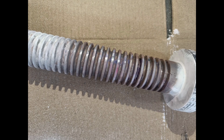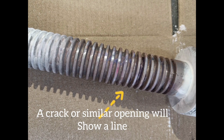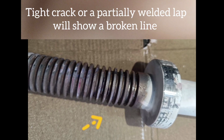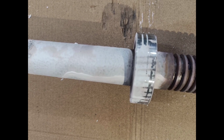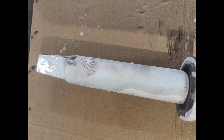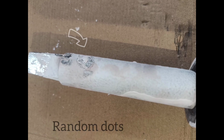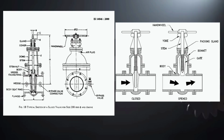Result. Usually, a crack or similar openings will show a line, and tight cracks or partially welded lap will show a broken line. Gross porosity may produce large indications covering an entire area, and very fine porosity will be indicated by random dots. This is how the sluice valve is tested as per the IS 14846.